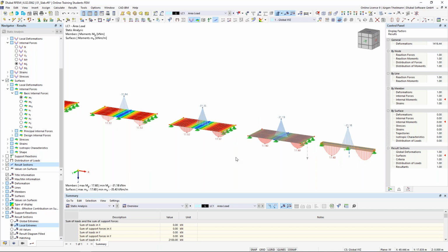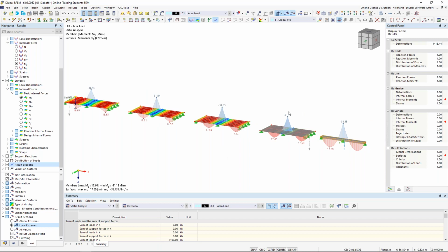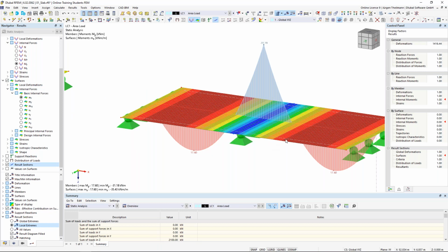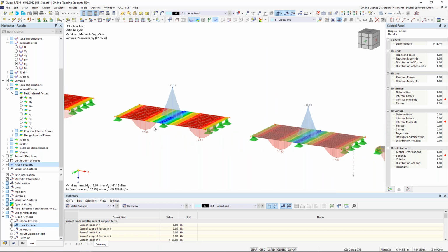And there is also, this is also a very crucial point for you as upcoming engineers to get to grips with, that you don't necessarily have to make the mesh as fine as possible, because when you make such fine meshes, you take a lot of computing power. And you will see from these two surfaces here, from the left one here to the right one, there's not much difference in the results, but a lot more calculation done on the right one.